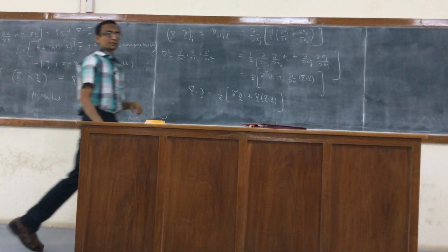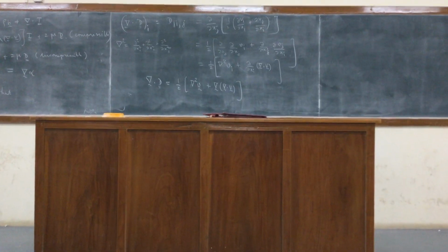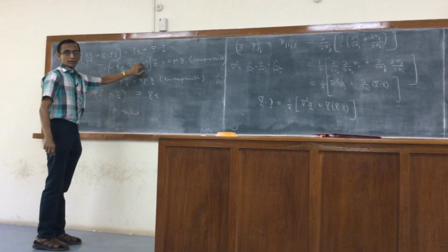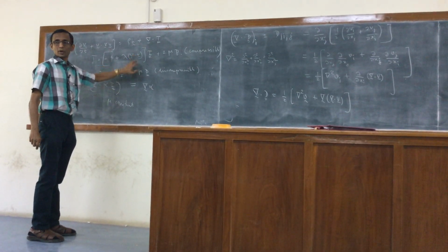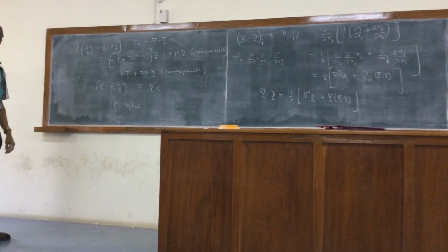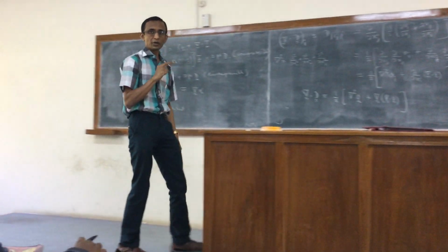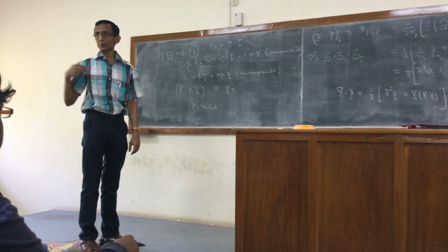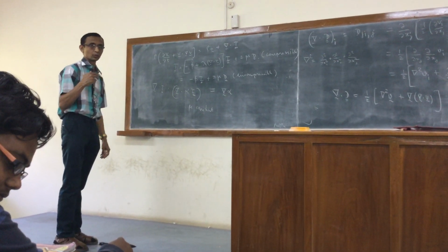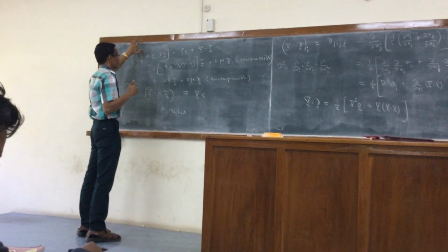It's fairly straightforward. So now we'll focus on the compressible fluid, because for the compressible fluid, if I put the divergence of the velocity to be 0, I get the equations for the incompressible fluid. At least to get the equations, that procedure is fine, but you have to always remember the different role played by the pressure in the compressible fluid as opposed to the incompressible fluid. So there is a big difference in the way you solve the equations. So now everything together.